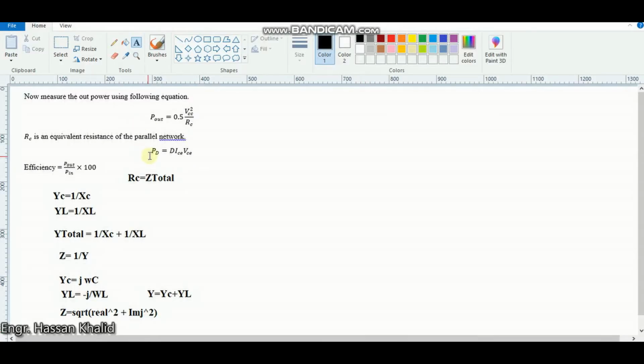Now the power dissipation, as we evaluated in lab number 10 when we were justifying the class C amplifier circuit, is equal to the duty cycle, which is the on time divided by the total time, multiplied by the saturation current ICE and the saturation value of the collector to emitter voltage VCE.